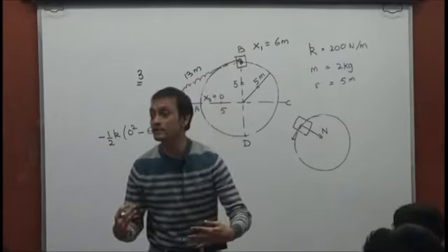There are no other forces acting on it, right? And this, from a work-energy perspective, must be equal to the change in kinetic energy of the system. That means half m final kinetic. Let's say the collar has a velocity v when it arrives at A. So that must be half m v squared minus 0 squared.